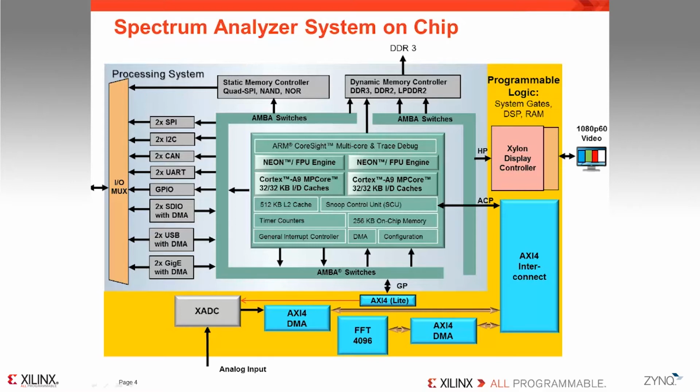This reference design includes an integrated software and hardware design demonstrating streaming video processing. We use the same Linux kernel as provided without rebuilding, the video display pipeline, the example graphical user interface, and software application as a starting point. To this design, we add a DMA engine to acquire the ADC data and pass it via the accelerator coherency port, or ACP, interface into the L2 cache.